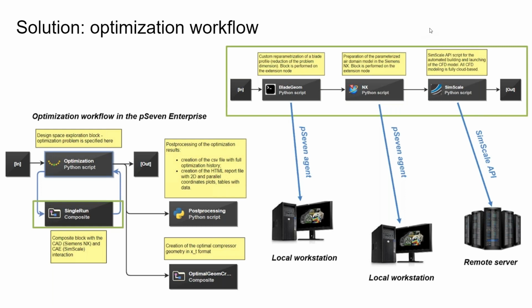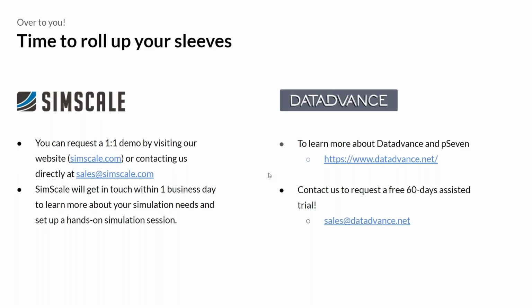Of course, this simulation could have used cyclic symmetry, but actually there wasn't much of a reason to use cyclic symmetry in this situation. The simulation was quite fast and straightforward. As Nikita said, the simulation that we were running here only took 3 minutes to complete using the entire geometry. Obviously, if it was a much more complex geometry, you could benefit from using symmetry.